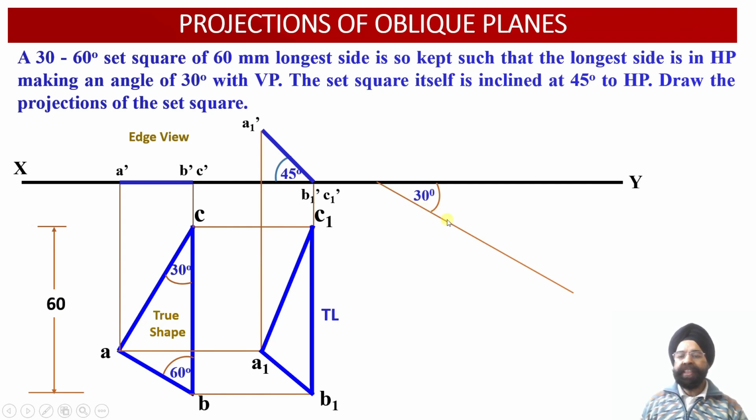Now onto this inclined projection line, we have to reorient this apparent shape of the triangular lamina in such a way that onto this orientation we should be able to obtain this particular edge, that is B1 C1, alongside this particular inclined projection line, right? So we have to reorient this triangular lamina over here in such a way that we are going to locate edge B1 C1 as B2 C2 over here. So B2 point will be located.